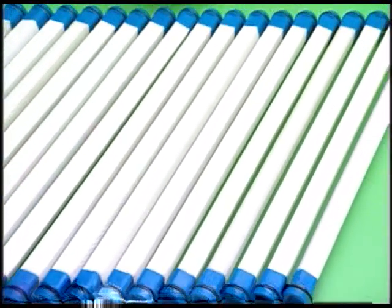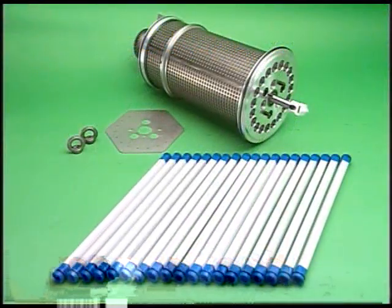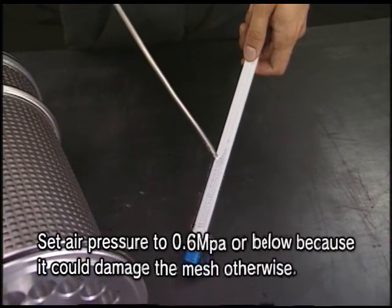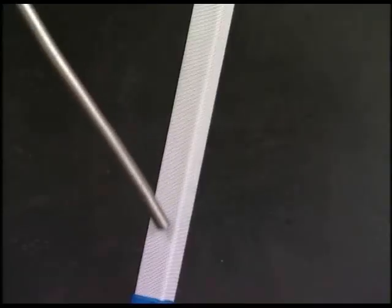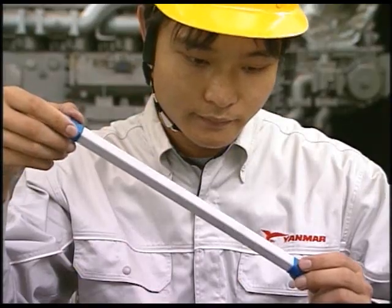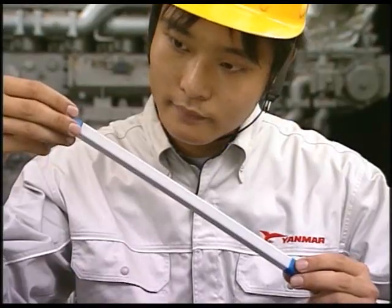Leave the pulled out filter element soaked in the cleaning agent for 24 hours. Conduct the cleaning by blowing compressed air from the outside of strainer element. It is more effective to use hot water of high pressure instead of compressed air. Conduct the visual check after cleaning. Replace any parts with scratches or dirt.